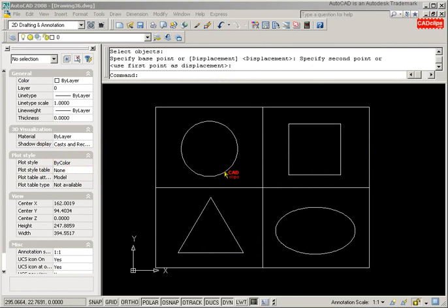In this lesson we're going to start to talk about layers, and layers we use to control the visibility of objects in our drawings. We use it to control color of the objects and line type, dashed lines and hidden lines and phantom lines, and we also use it to control indirectly the pen weights and the line weights of our plotted objects, because generally color will indicate the line weight or pen weight. That's how we get our definition in our drawing to look nice.